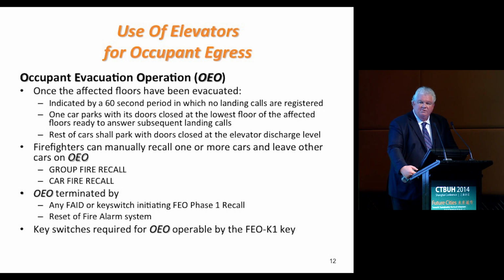Now, with firefighters' emergency operation, that system has always worked on a particular group of elevators. Now we've added the ability for firefighters to recall one car at a time. So they have a choice of the whole group, or they can recall one car. They can use 1 or 2 cars for firefighting duties and leave the rest of the cars still operating in occupant evacuation operation.